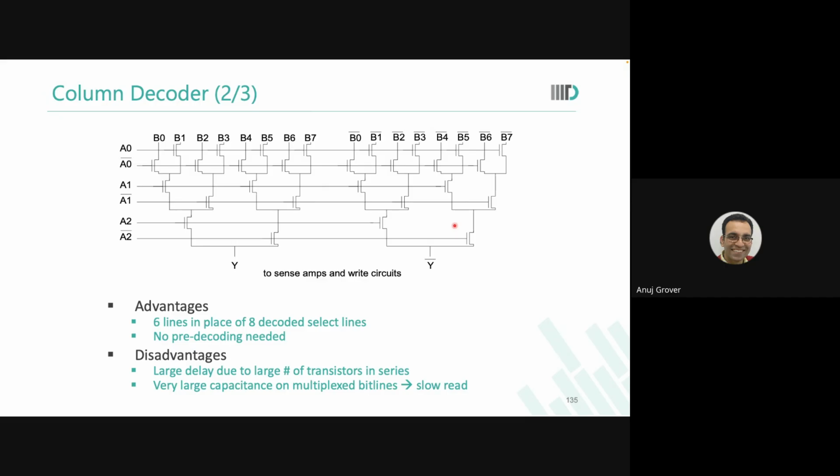What you may still decide is whether to place the sense amplifier before the second stage of MUX or after it. If I keep it after the second stage of MUX, I still have to pass 2 pass gates, and the disadvantage of large intermediate bit lines continues, and my read access will become slower.